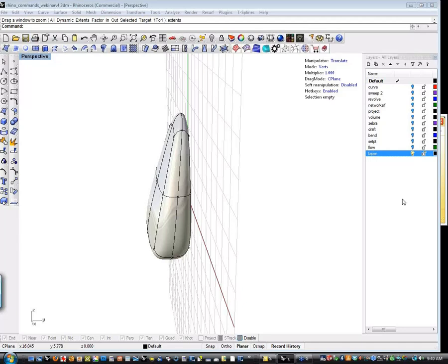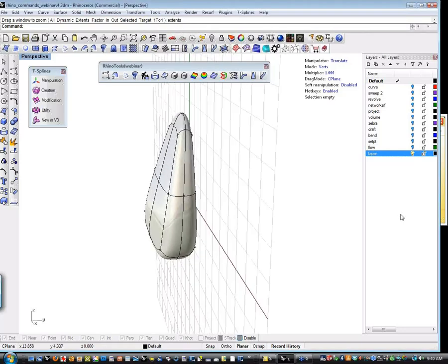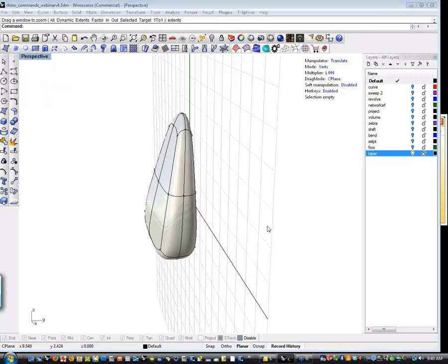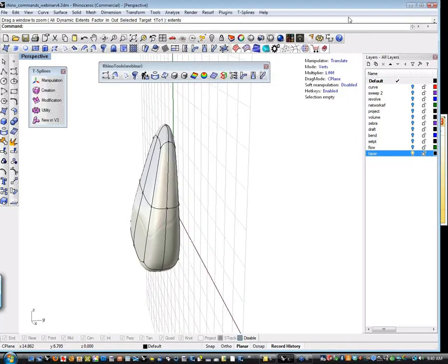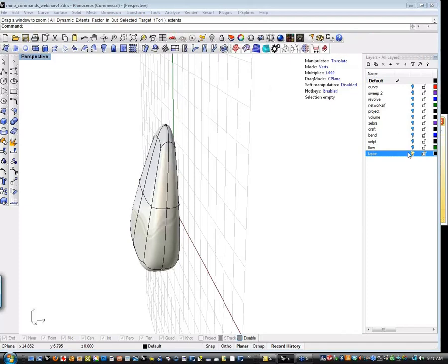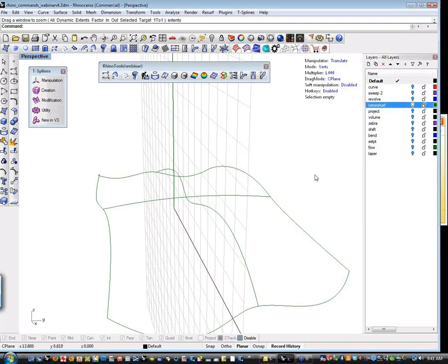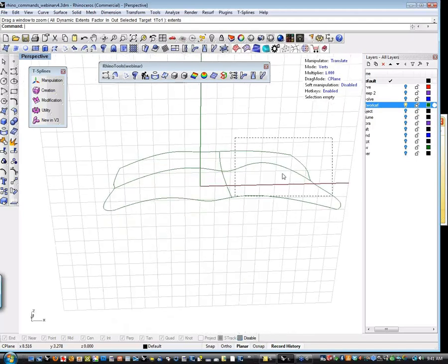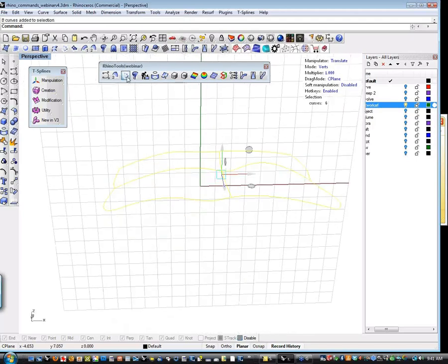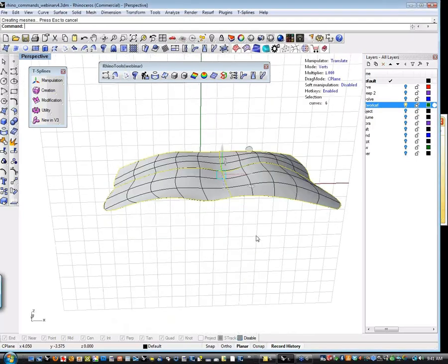There's one in here. It says, is there anything like fit surf inside of T-Splines? I often convert NURBS to TS object and end up with too many faces. TS fit surf would really help to reduce face count. Basically, the way to do that is if I go back to my network surface here, this gets a big fat surface with lots of points in it.